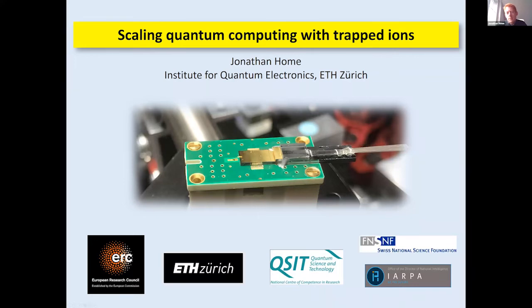There's a bunch of wire bonds that you can see attaching to the chip here. But on the right-hand side, this slightly more messy structure is actually a bundle of optical fibers, so 8 optical fibers, which go into a V-groove array, and they're then coupled into this chip in order to deliver light to the ions. And so that's a relatively new approach, and I'll tell you some results that we've had recently from that approach.